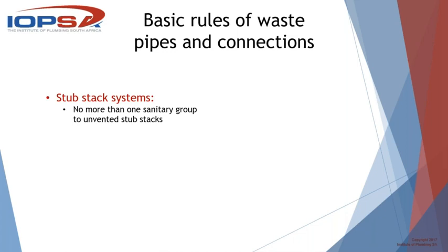A one pipe system is the one we most commonly employ in most buildings, because of the cost factor, and if properly designed and installed, it can work perfectly well. That'll also be a fully ventilated system, so the same discharge stack also acts as the ventilation stack.